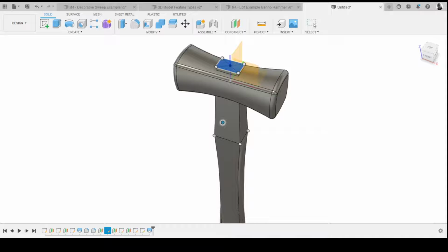Now I've missed one crucial step, which is just a bad habit of mine. I haven't created components from the outset, so I'm working all in bodies here. So apologies for that. I'm still trying to remember to work in components. I used SolidWorks for years and it worked completely differently. At the moment, if I do this, it'll join the hammerhead and the handle all together as one. So in operation, I'm going to create a new body for this particular tapered loft. So if you've rushed ahead and joined it, go back and turn it into a new body.